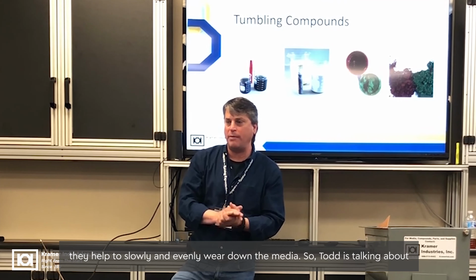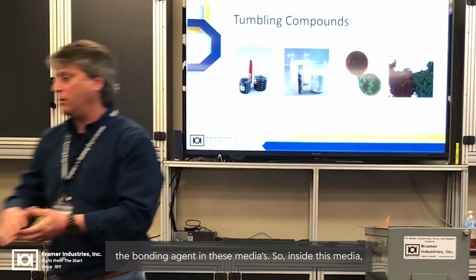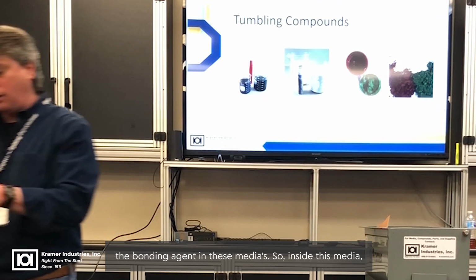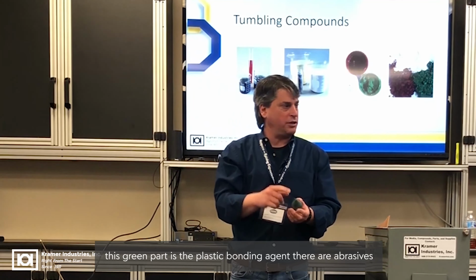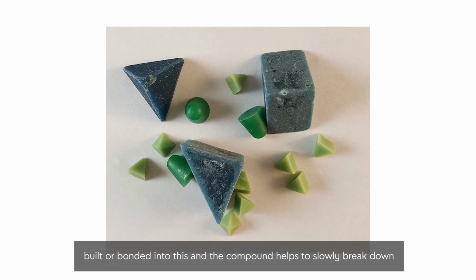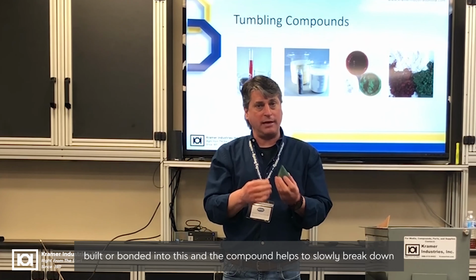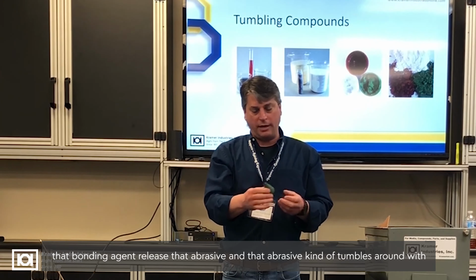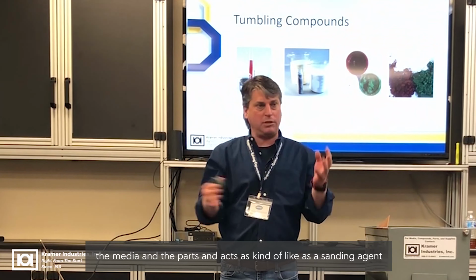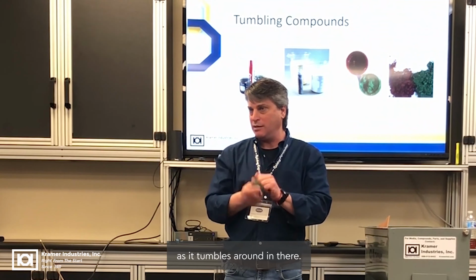So Todd was talking about the bonding agent in these medias. Inside this media, this green part is the plastic bonding agent. There are abrasives built or bonded into this. And the compound helps to slowly break down that bonding agent, release that abrasive, and that abrasive tumbles around with the media and the parts and acts kind of like a sanding agent as it tumbles around in there.